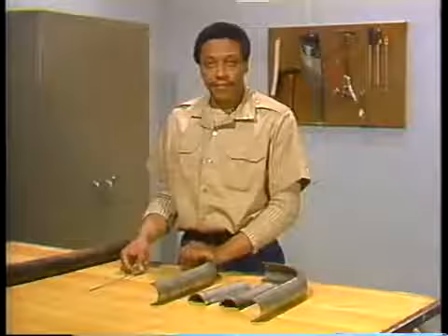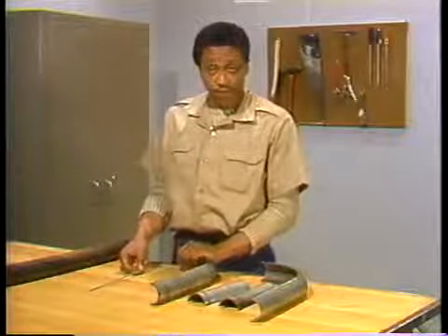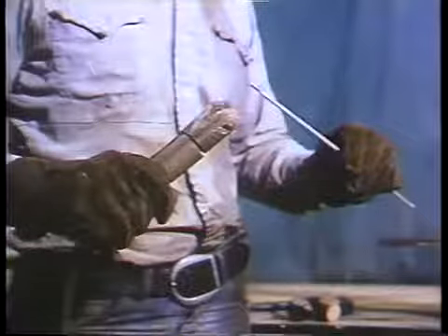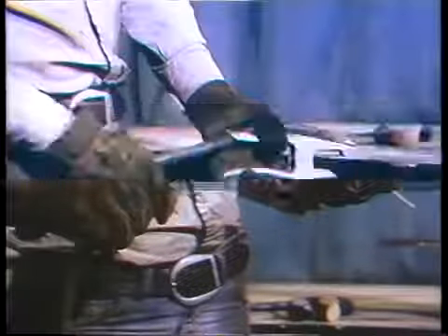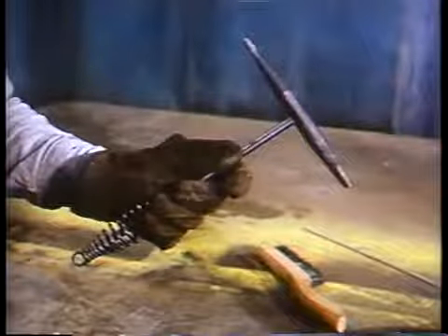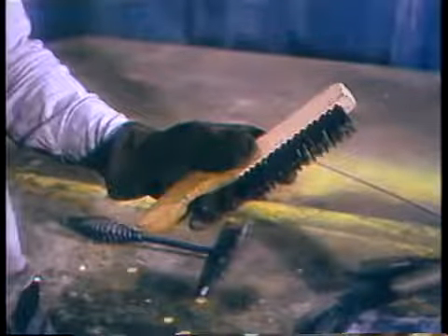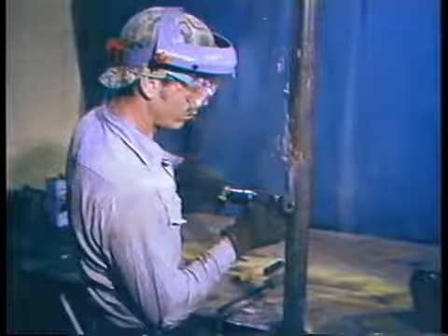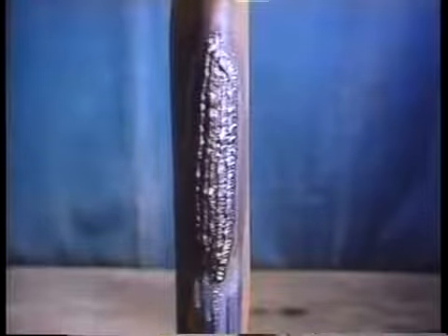That ends our demonstration of the clad patch procedure. Remember, the tools and equipment you'll need to do a clad repair are weld rod and a rod holder, a grounding cable, a slag hammer, a wire brush, and a grinder. The steps in the repair are clean the area to be clad and apply the weld metal. Again, cladding is used to thicken and reinforce the tube wall. It's used to repair tube thinning caused by corrosion and erosion.